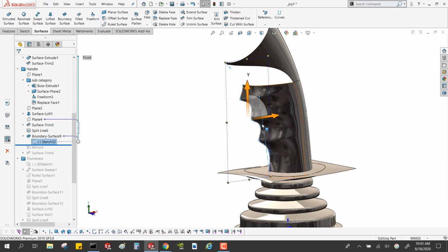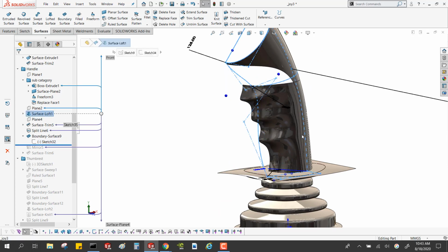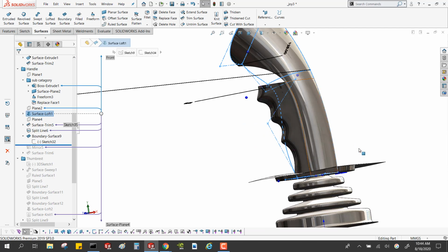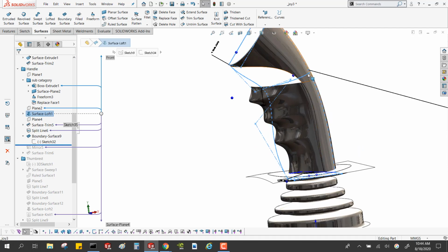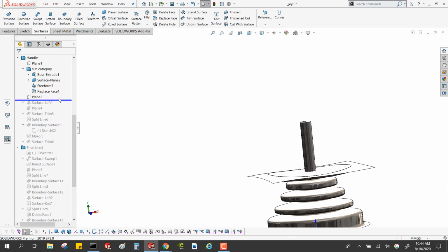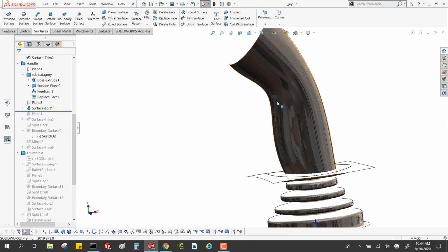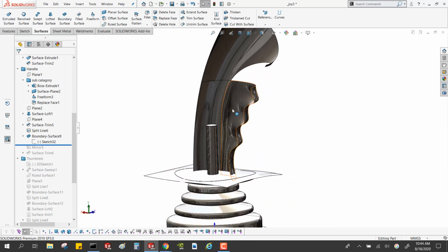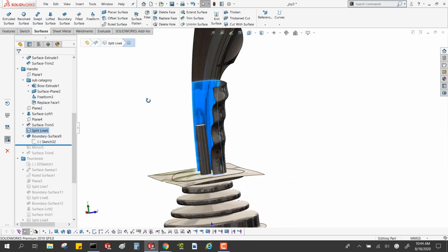If I had tried to put the finger ridges in when I was doing the loft, as the loft was going up, those finger ridges would have affected the backside of it too. When you're dealing with something like a loft or a sweep, and you're pulling in different directions, trying to keep things tangent in different directions, a lot of times you'll end up affecting geometry you didn't want to. So that's why I did the surface just as a quick flute with a little bit of an indent for where the hand goes, but I didn't try to put in the finger ridges until I put them in independently so they wouldn't have any effect on this surface.